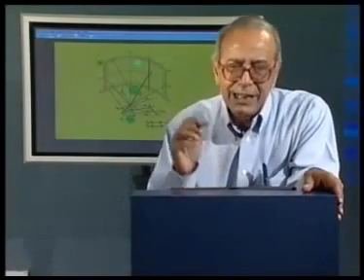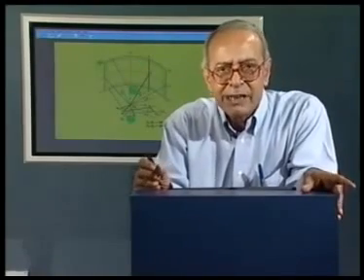Once we get the extreme positions of the point C, I draw the wiper blades, which always remain vertical because of the parallelogram linkage, as E2F2 and E1F1. Because of the parallelogram linkage, all the coupler points generate the same circular arc as O4C. Only thing, the center of the circle is shifted in a symmetric fashion from C2 to E2, that is O4 to CE, and C2 to F2, that is O4 to CF. These are all on the same vertical line. As a result, we get the complete field of wiping as generated by this particular wiping mechanism.